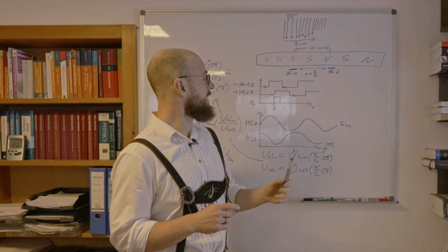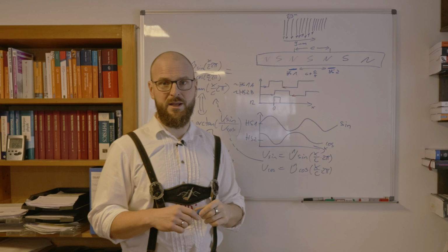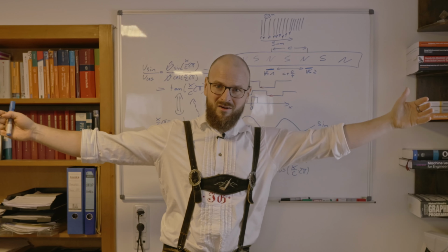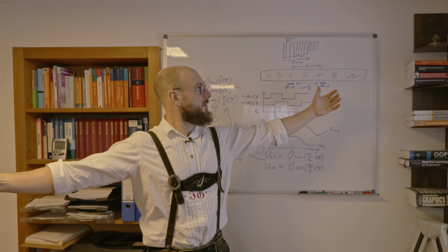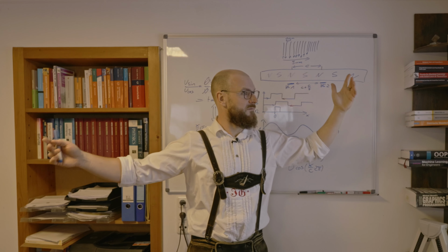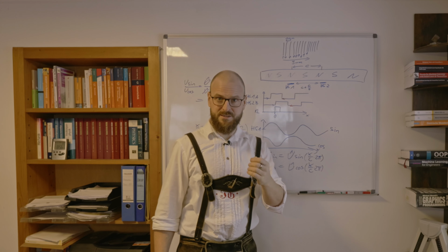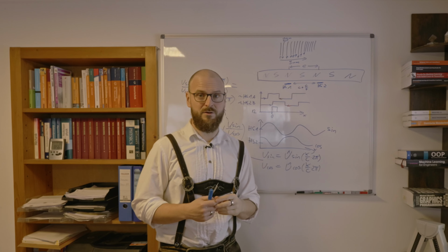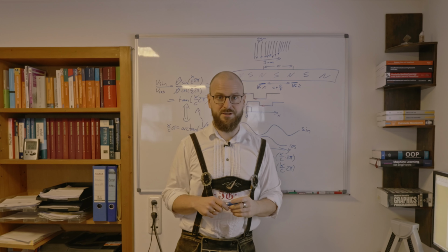On the other hand, we have a simple and precise way, due to the interpolation, to define long distance measurements. So, in contrast to the strain gauges, which are very usable for measuring very short distances and distance changes, those incremental encoders are very good to measure large distance changes.